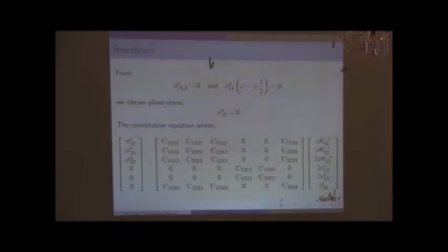So we are in plane stress for the leading order stress, and now I can write the constitutive equation. I have separated the in-plane components from the out-of-plane components, and those zeros come from the monoclinic symmetry of the plate.